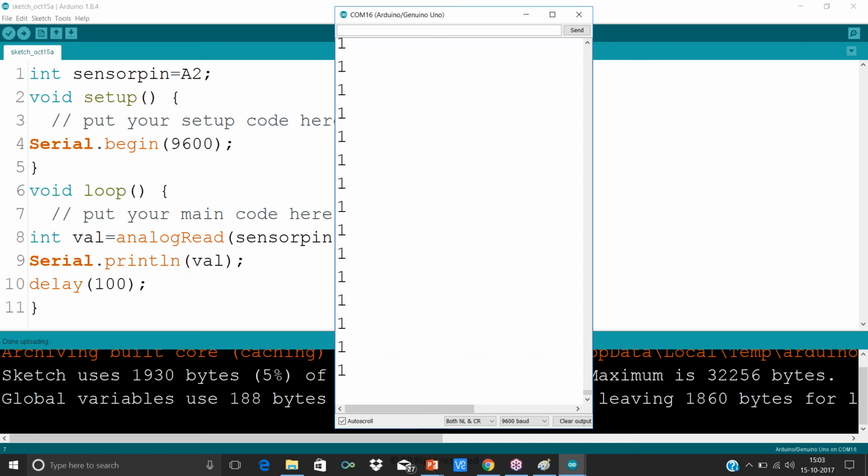Now you're getting an error. All right. Do one thing, ma'am. Close the serial monitor which is displayed here. This is called the serial monitor. Close this, remove the USB from your PC and reconnect the USB. Then open the serial monitor again. Let me know if the error is resolved or not.